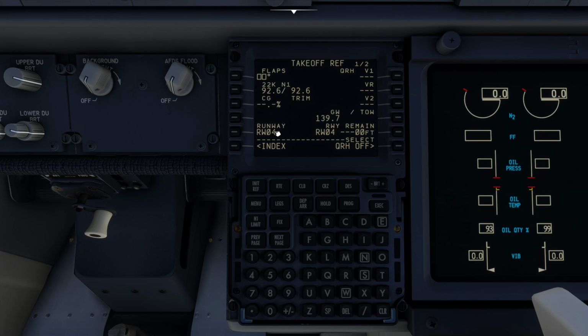So we're going to configure the airplane's takeoff roll. So we're going to say 5 degrees of flaps, which is standard for a 737. And then we can click the next to these three numbers that have just been generated. These are the V speeds. The one we'll take notice of is the VR, which is the rotate speed. So when we click each of these buttons, it copies it across. So these are the numbers that will appear next to the indicated airspeed ribbon when we're rolling down the runway, and we know when we get to 129 the co-pilot will shout out rotate.